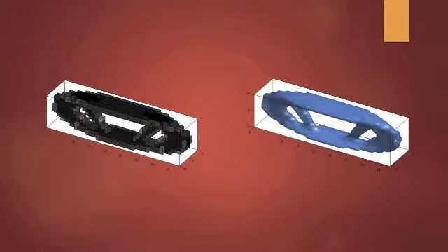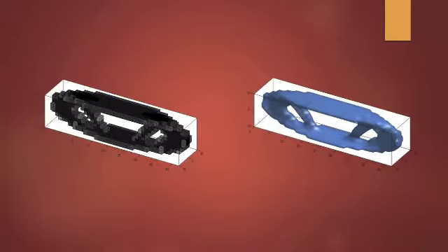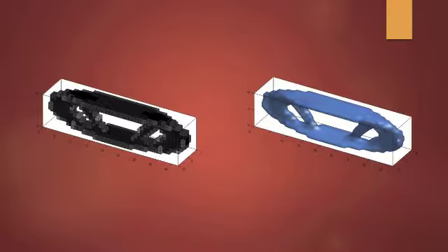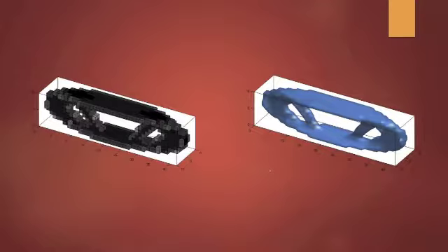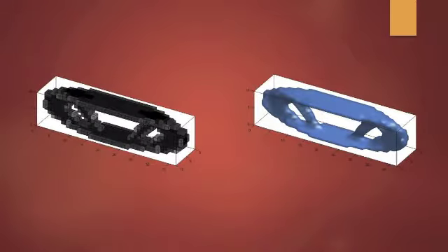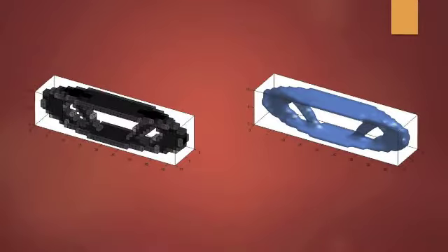In the results here, we actually have a 3D object that we can model using 3D tetrahedral elements, as opposed to the previous case of legs where we ended up analyzing the structure using beam elements. One of the issues with the structure that we have here is that the force applied on the beam is not constant. It is not straight down, and kids actually swing when they sit on a swing.